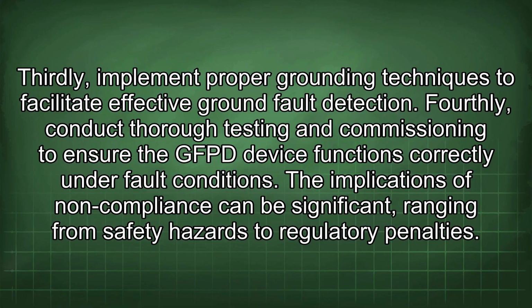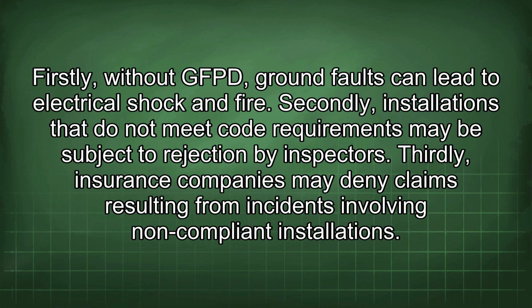The implications of non-compliance can be significant, ranging from safety hazards to regulatory penalties. Firstly, without GFPD, ground faults can lead to electrical shock and fire. Secondly, installations that do not meet code requirements may be subject to rejection by inspectors. Thirdly, insurance companies may deny claims resulting from incidents involving non-compliant installations.